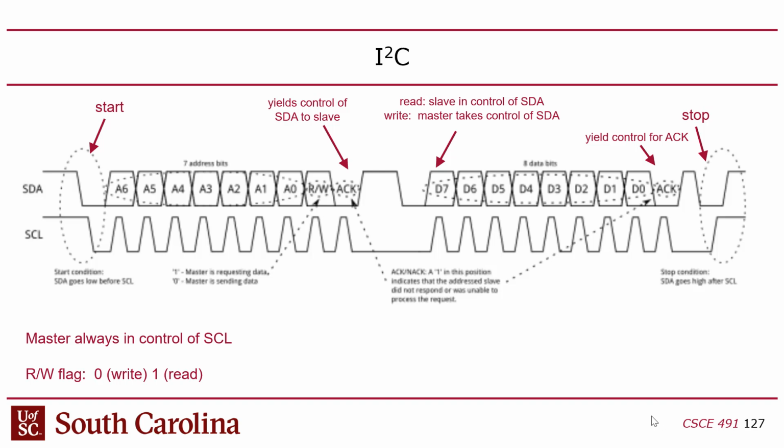Unclear. I don't know. Never seen a reference to that. But there's probably some minimal amount of time you're supposed to keep that high, right? What's a good rule of thumb? I don't know. In lab 2, I have found that 10 microseconds is how long we hold it high. That was only from trial and error, and that had to do more with the capacitance and how fast the chip could toggle that. I don't think it has to be high very long, though. But it depends on the timing characteristics of the latch they're using to sample it.